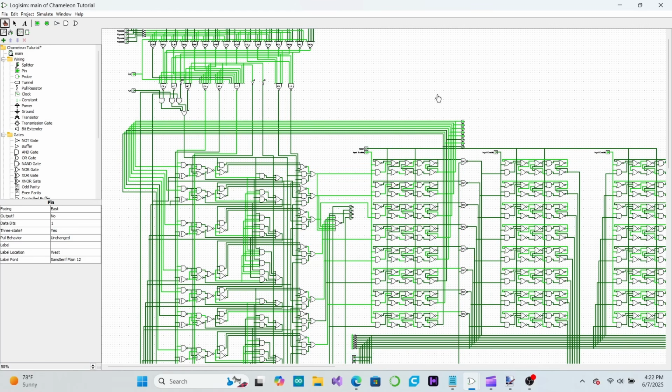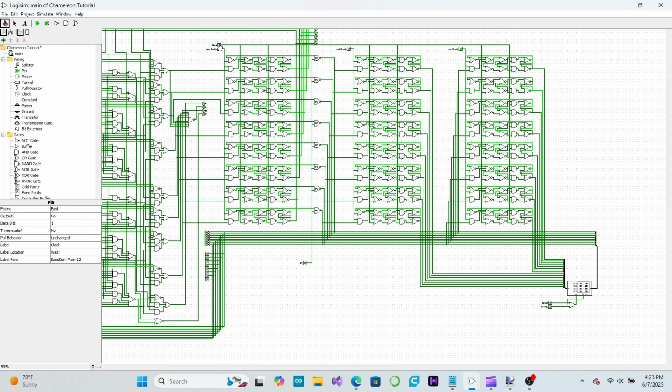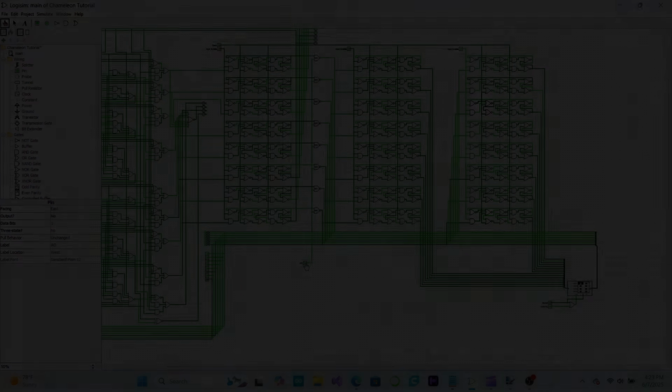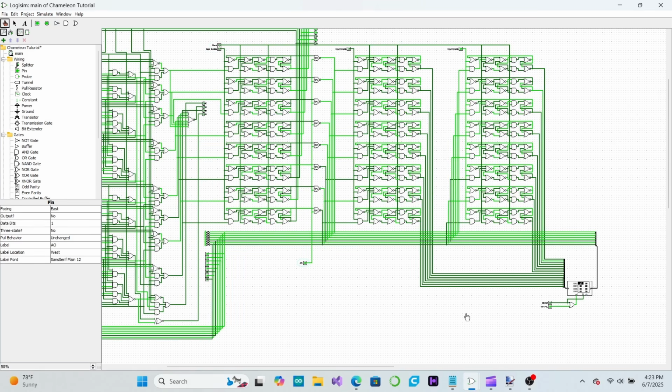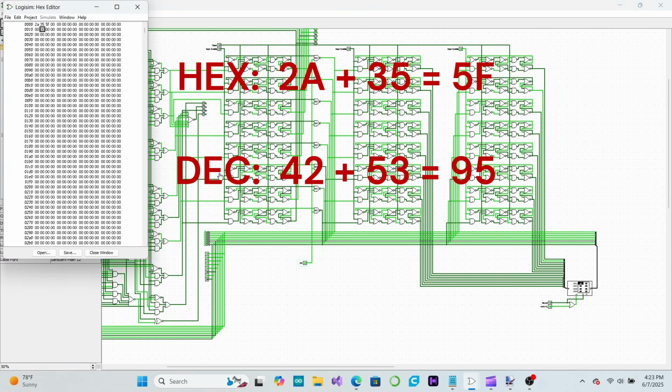Now we'll set the data bus to 2 and load the value into the address low register just like before. Finally, we will set the write signal, the accumulator's output enable, and cycle the clock. The value 95 should be written from the accumulator into RAM at address 2. We have just added the value in address 0 to the value in address 1 and stored the result in address 2.